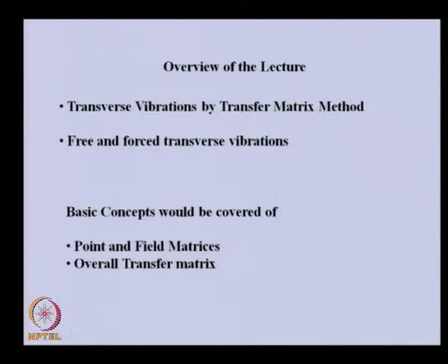Transverse vibration by the transfer matrix method: we can analyze both free and forced vibration. Similar to the torsional vibration case, we will develop point and field matrices for transverse vibration, and we will have the overall transfer matrix concept, and then we can apply the boundary conditions of the problem to solve either free vibration or forced vibration.